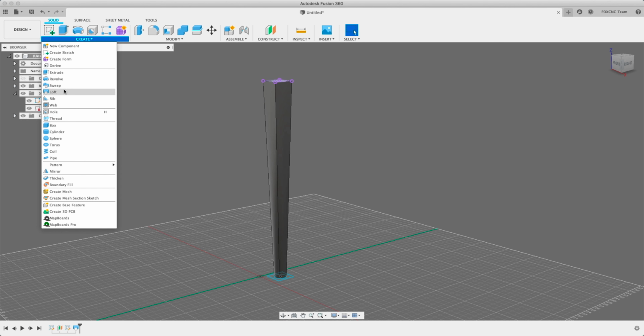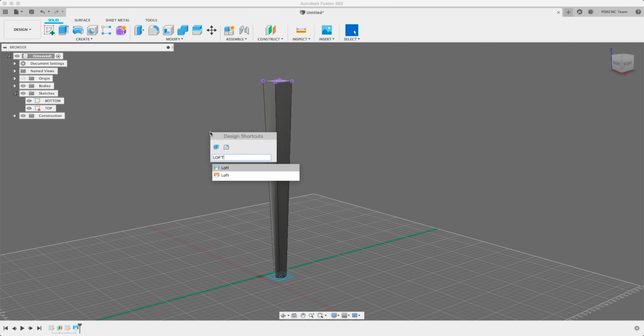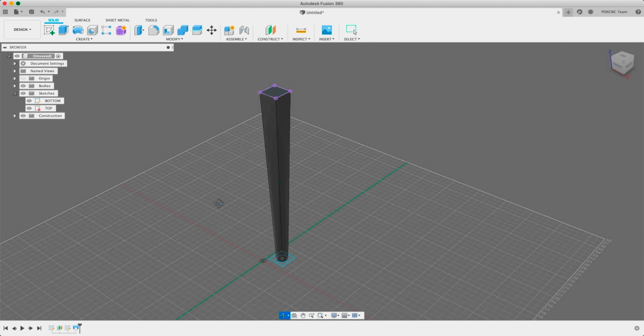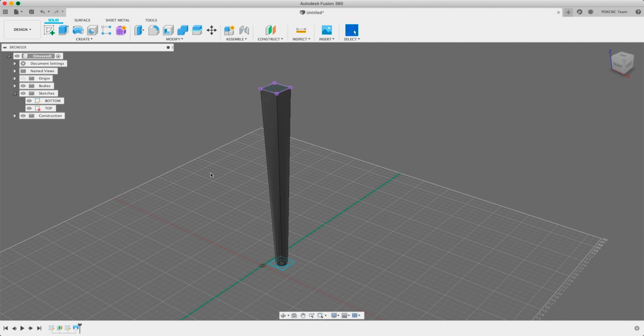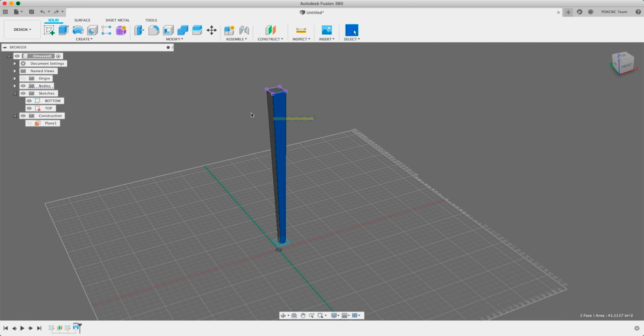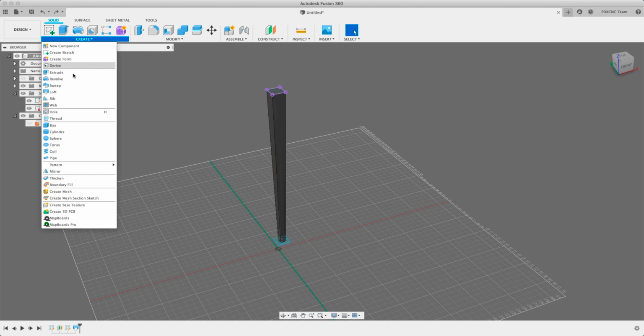Again, you go up to create loft, or our little shortcut here is S, and type loft, enter. Now we're right into loft. That's pretty much how I use anything I don't know a key command for already. All right, so we have our table leg we've made with our loft command. Next up, let's put a top on this, and we're going to look at the sweep command.